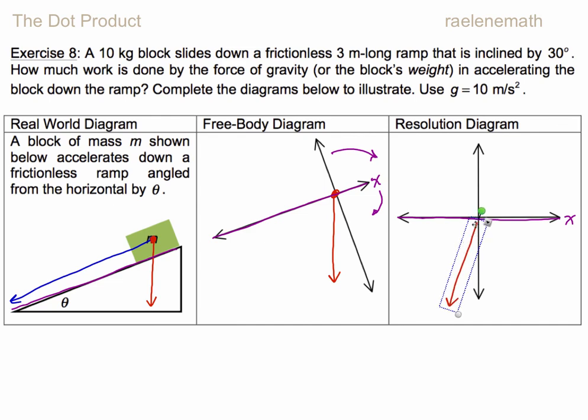And from here I can see this force vector has a horizontal component and a vertical component that lie along the y-axis and the x-axis. So in order to resolve the force vector, we create a right triangle to each axis, and we can therefore see a vertical component of force F, we'll call that Fy, and we can see a horizontal component, which we will call Fx.